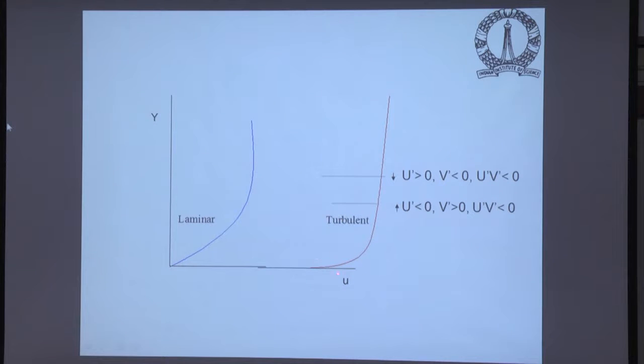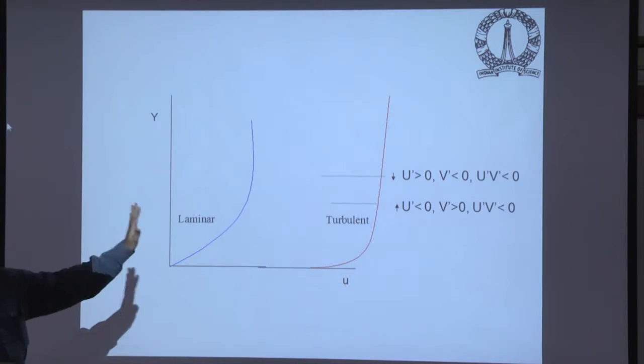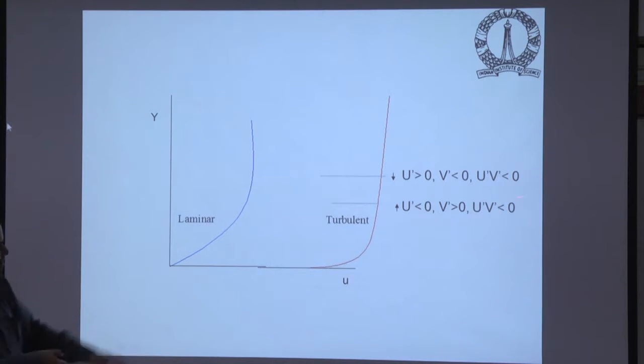In the case of turbulent flow, it's a lot fuller as compared to that. You see here, it's less full, whereas here it's a lot fuller. On an average, instantaneously, of course, what would you see? If you look at a turbulent flow, this is like a time average frozen picture, so to speak, in time. This is how it will look like, average picture. And as Professor T.S. was mentioning in the morning, you can see that this region is almost like an inviscid flow profile, except the region close to the wall where you have sharp gradients.